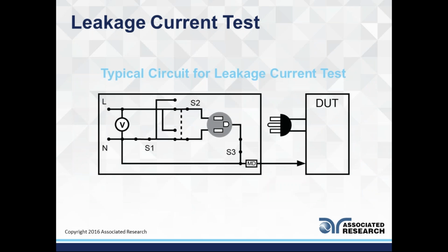This is a little diagram, a circuit schematic. Right now looking at it might be confusing, but hopefully by the time we're done with this you'll understand what all these fault conditions are. So let's establish where we're at. This is the line neutral of where your DUT is being powered up. It can be referred to as your T1 in most standards. You can think of this line neutral as the power coming from the wall when you plug in your device, but it's going to be at 110% of your rated voltage. So if you're rated at 120, you must be testing at 132.